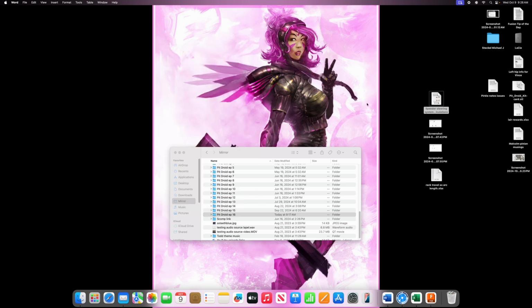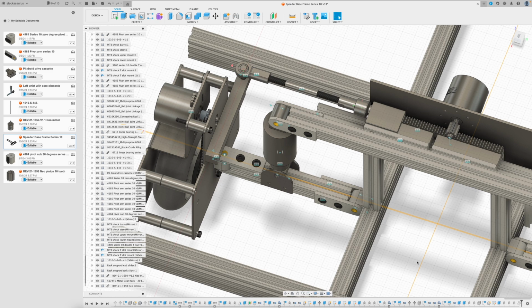So I'll get into the theory a little bit, but for right now, let's actually look in Fusion at the actual construction as it's designed right now. So we've got our wheel assembly here, or drive wheel. This is the steering arm. So you'll note that the steering arm does not come off at an angle. That angle, called the Ackermann steering angle, is necessary. The steering arms have to come off at an angle when you have both wheels connected together. But since I am separating the wheel steering systems into two separate systems, it's actually a lot simpler geometry just to make the steering arm come straight off of the wheel.